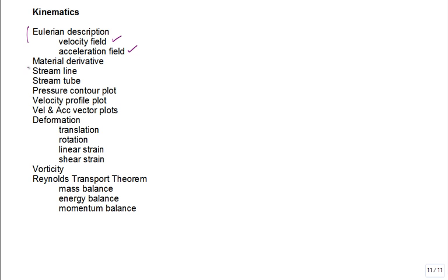Then we had this really difficult concept, material derivative. What's that all about? This brand new notation. True? It accounted for not only a local acceleration due to how it changes with time, but also an advective or material acceleration, if you want to use it.